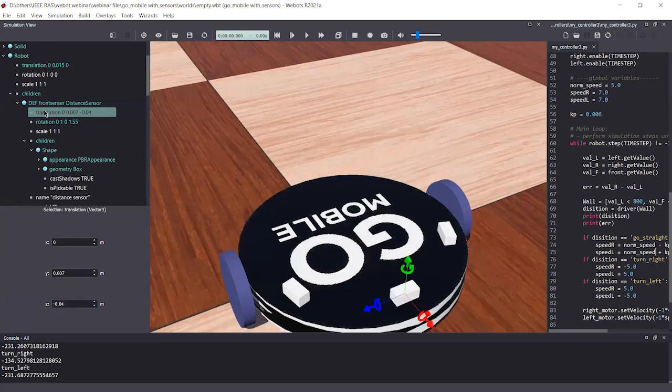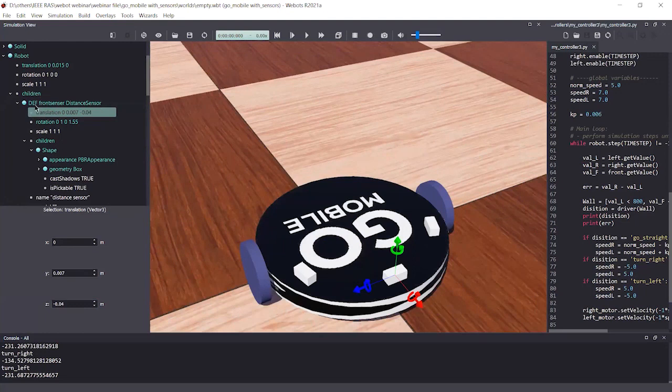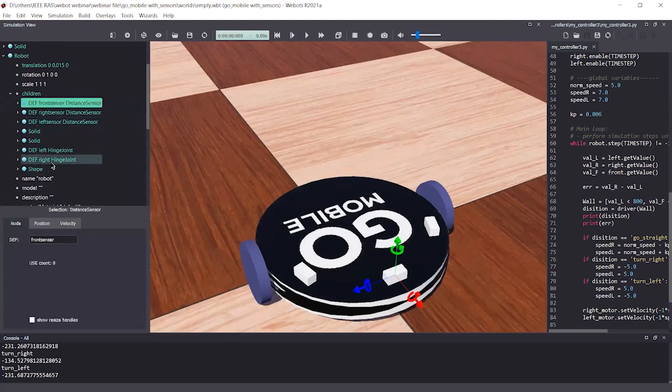Similarly, we can copy this sensor using Control C and paste it to the other sensors, like we did in our solid and in wheels. When we were adding wheels, we used that technique. So similarly, you can add the other sensors as well. Sometimes you may have the file with you as well, and you can open that if you want. So now we have 3 sensors.